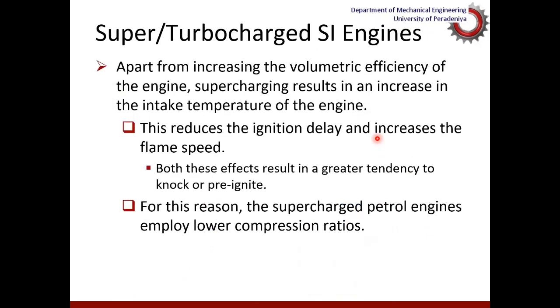Now, as I mentioned in my previous slide, superchargers or turbochargers in SI engines is quite a challenge, because if you increase temperature at the beginning of the compression or combustion process for that matter, then definitely the tendency for knocking would be increased.